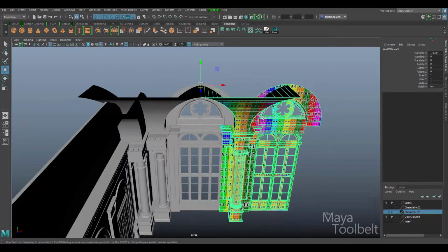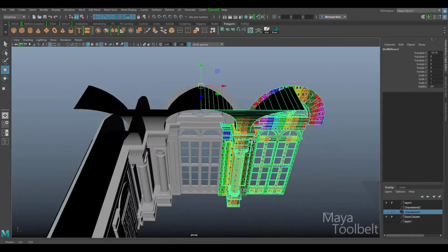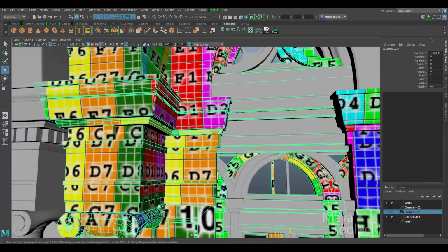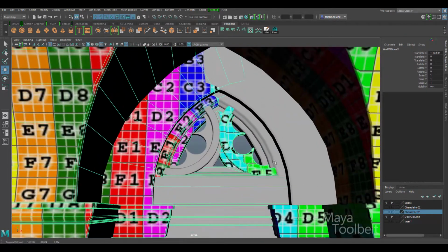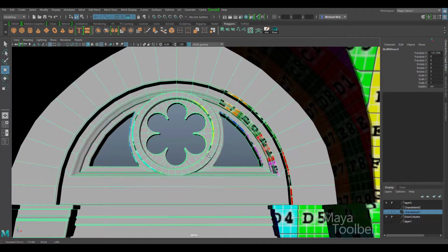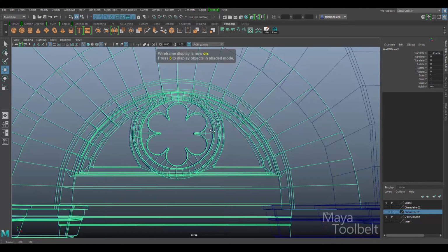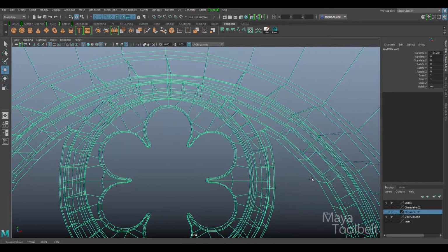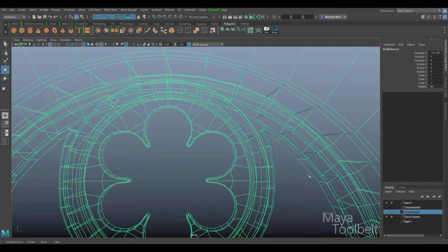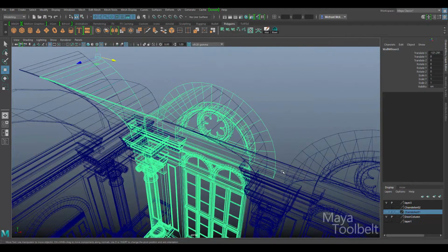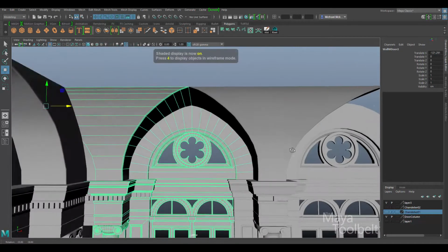But we're going to go ahead and duplicate it, hit Control D, and then move that duplicate over here like this. I'm going to zoom in here, and I'm middle mouse clicking and dragging to move these over. You can see I'm going to get it right on top of the other. I'm going to wireframe just so I can ensure that we're right on top, just like that. So I'm right there on top of the gray version of what we have here.